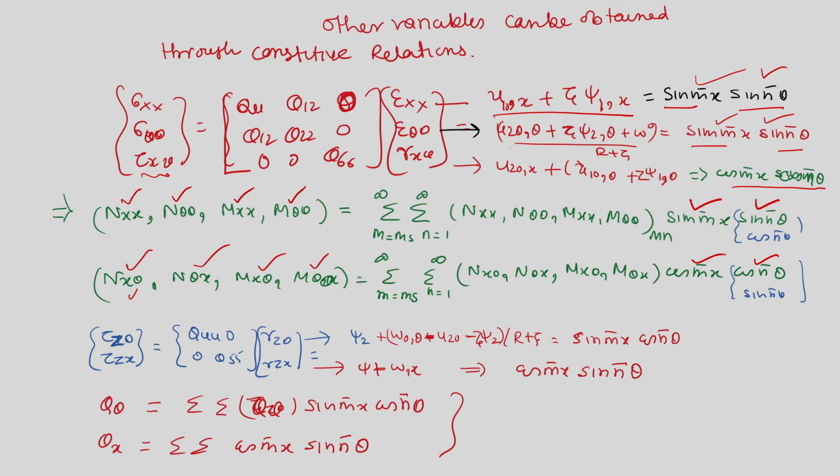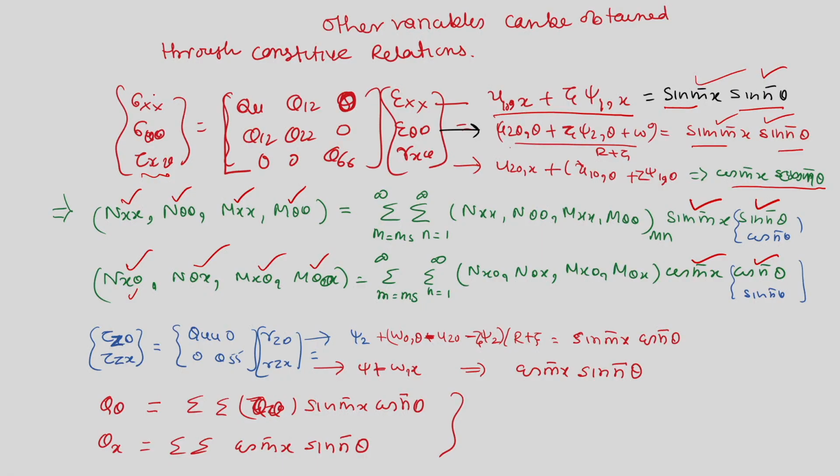We will solve the displacement, but at the end of the day we are interested in finding the variation of stress resultants or the stresses. So, this will give you the actual variation. Definitely there will be some magnitude, basically sigma xx mn or nxx mn, but they will follow this path, this mode type.